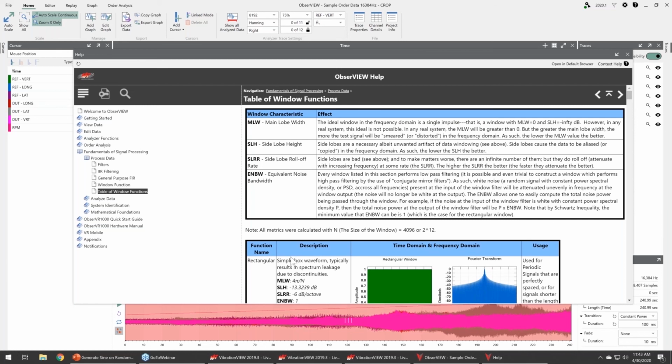So since you have multiple sinusoids, does this reduce test time compared to a single sweep? Yes, just like sine-on-sine testing, which is becoming more and more common in Europe, where rather than running a single tone from 20 to 2000 hertz for, let's just pick a good number, 12 minutes, I can divide that tone into 4 parts and run 4 tones over that frequency range. It's very dependent on what you're doing and the application. But in effect, yes, you can reduce the test time of a single sweep by dividing it into four tones running over the same frequency range.